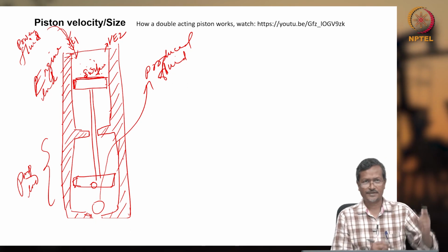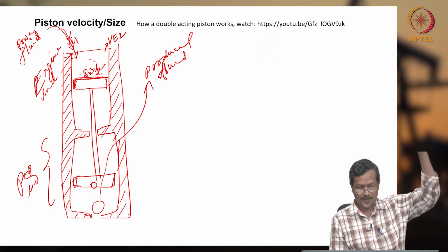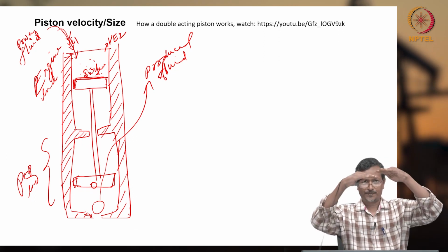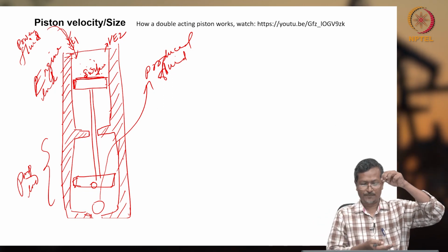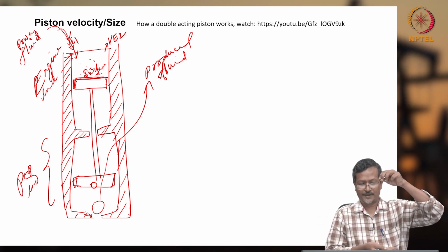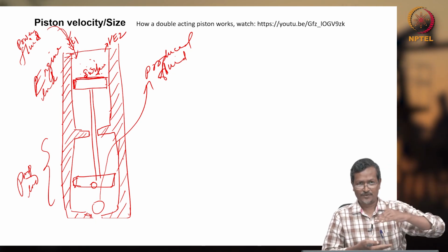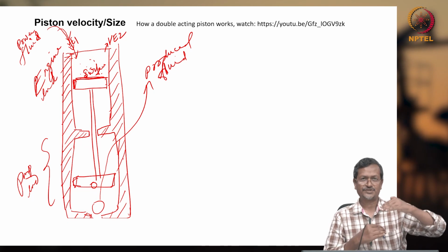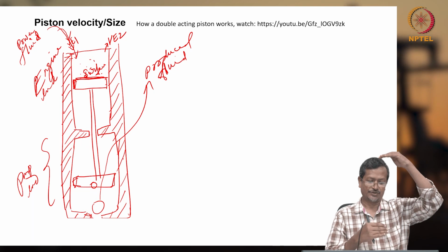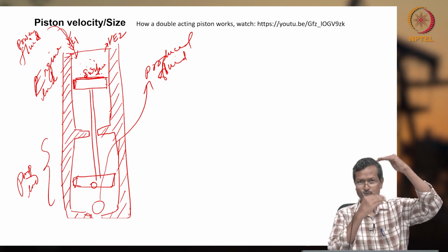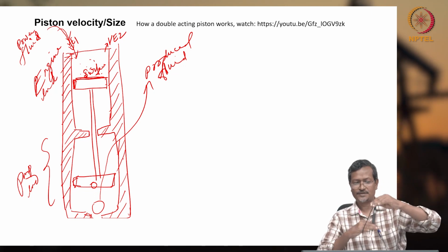From where is the power fluid coming? It is coming from the surface. We have a high pressure pump on the surface, so that pump is delivering high pressure fluid. So that fluid is pressurizing the piston. The piston is moving down. That piston is connected to your plunger assembly for the pump. So the pump will be delivering fluid when the piston moves down, and pump delivering when the piston moves up. The engine piston and your plunger for the pump are both connected, so both will be moving together, right? Moving down, it is delivering.